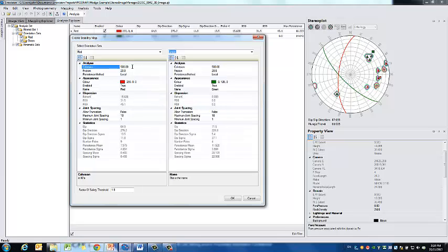And again we have some other geotechnical parameters we can input into the software to contribute towards the definition of the wedge, or which will determine whether the wedge is unstable. So in this case we have cohesion values and friction values, which is a critical friction angle. As I said before, on the domain we have pore pressure and rock density also. So all of these values are taken into account by the software when it tries to calculate whether wedges exist and whether they're actually unstable or not.